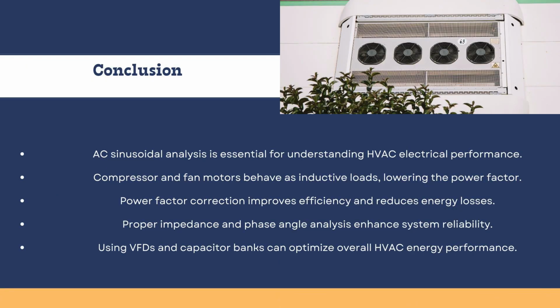For conclusion, AC analysis is essential for understanding HVAC electrical performance. Compressor and fan motors behave as inductive loads, lowering the power factor. Correction improves efficiency and reduces energy loss. Proper impedance and phase angle analysis enhance system reliability. Using VFDs and capacitor banks can optimize overall HVAC energy performance.